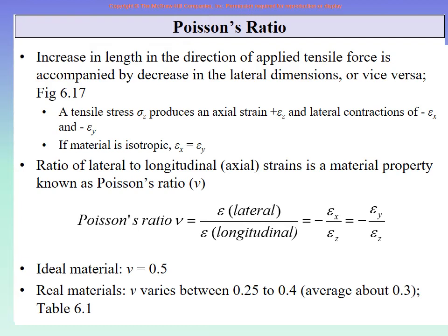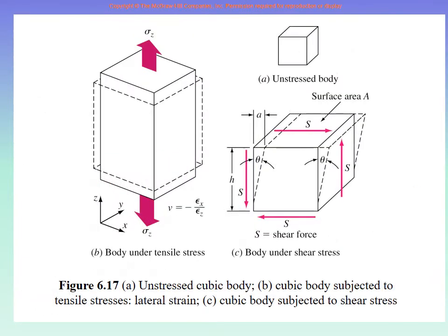Okay. So this is Poisson's ratio, and let me show you on the figure here. Forget about this one, this will come later on. So you see, there is a long piece, and it is square or rectangular in nature. This dashed line is the original size of the material, the sample. Now you have applied stresses in the z direction, the axial or the longitudinal direction.